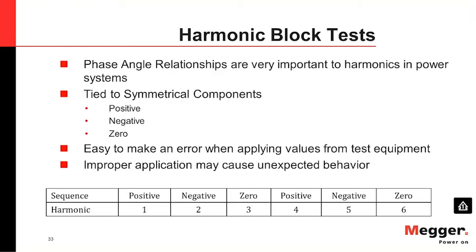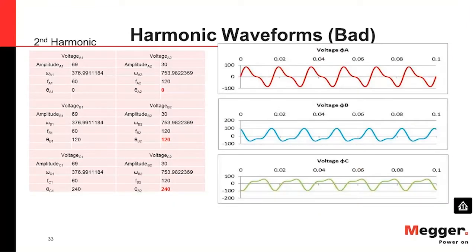Now this is something like what we are generating, because our equipment can generate harmonics up to 4 frequencies in the same injection. Means that we can superimpose those harmonics in the same injection. Like it's the same phase, I can put 4 frequencies together to end up with something like the harmonic we have seen here.